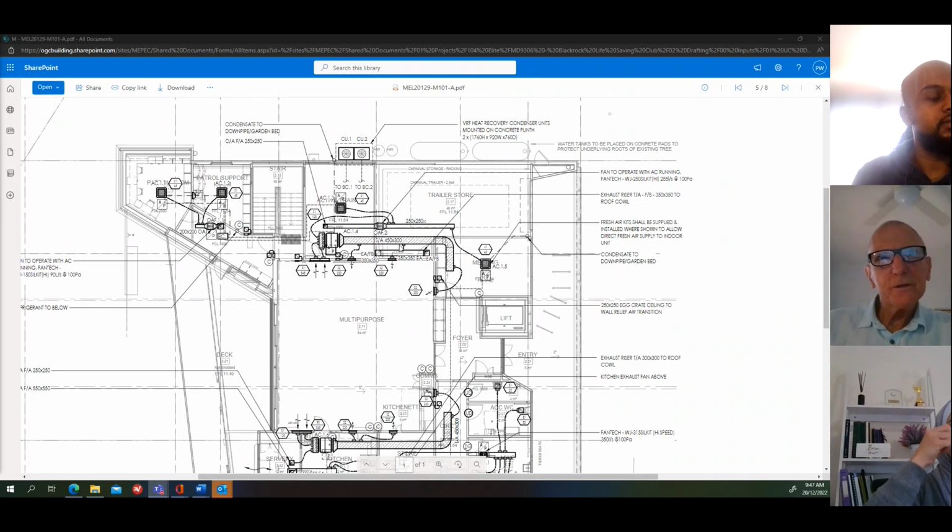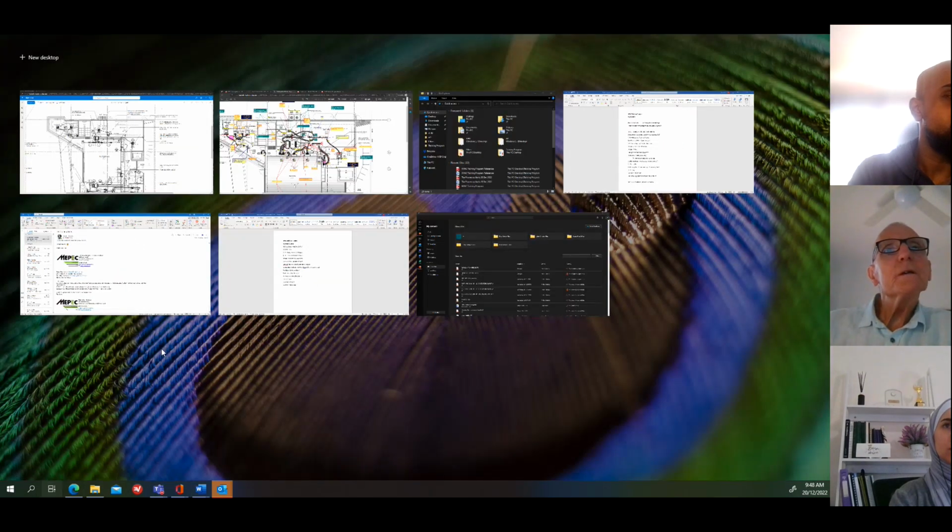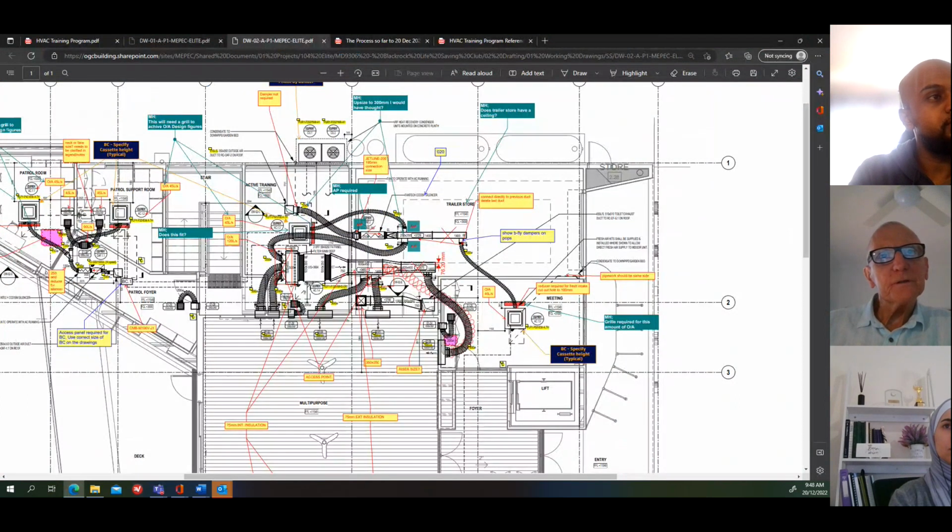So it's really important, because that can be a trap for new players to understand the difference between the two. It's not that difficult, but just don't forget that that's what it is. The workshop drawing will show the actual metal size, because that's what's going to be manufactured. So I'll go back to that one. So the 600 by 450 duct in this case. What does that tell you about the insulation thickness? 75. Correct. So you're adding 150 to each dimension.